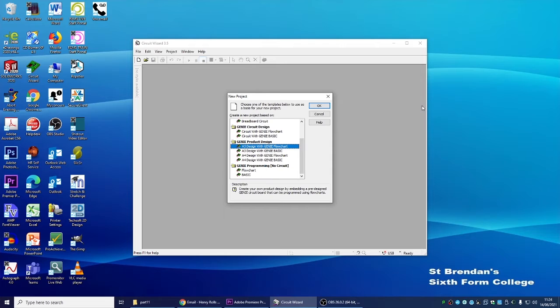But you might want to look at part 2, and look at slightly more advanced programming. For example, if you're going to do a flashing amber light, rather than just saying on, off in the flowchart, you might want to say on and off and repeat 5 times. Or you might want to wait for the traffic to flow for 30 seconds before the amber light comes back on, to allow traffic to flow through, like real pedestrian crossings do. That kind of condition. You can look at it all in the second part of this video, so the next video.